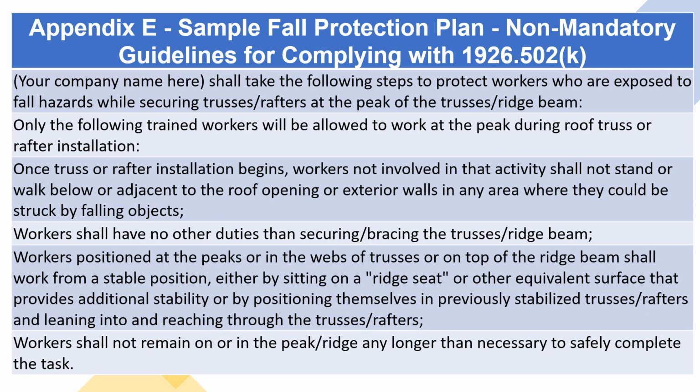Your company name here shall take the following steps to protect workers who are exposed to fall hazards while securing trusses/rafters at the peak of the trusses/ridge beam. Only the following trained workers will be allowed to work at the peak during roof truss or rafter installation. Once truss or rafter installation begins, workers not involved in that activity shall not stand or walk below or adjacent to the roof opening or exterior walls in any area where they could be struck by falling objects. Workers shall have no other duties than securing/bracing the trusses/ridge beam.